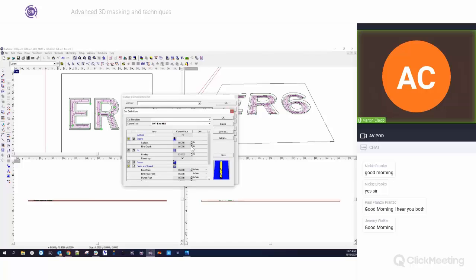Now, here's where we talked about our surface depth. Remember how we said that I milled the center platform for these letters to sit on. I milled them down about 0.125 inches. So that means that the surface is no longer at 0, 0 anymore. So I can do one of two things. I can set the depth at 0.25, and it might give me a similar result.